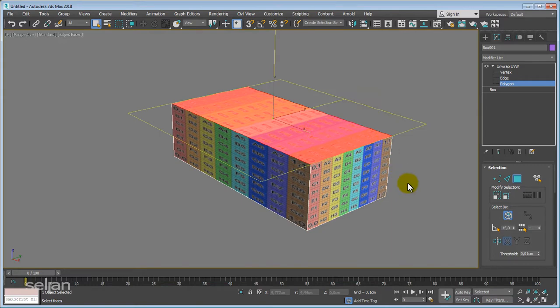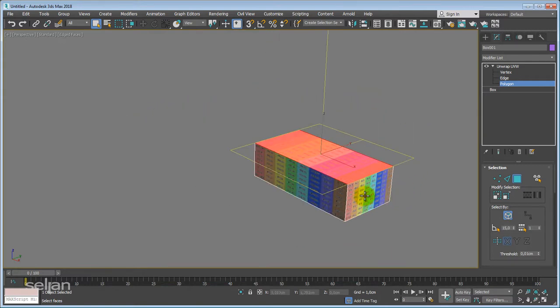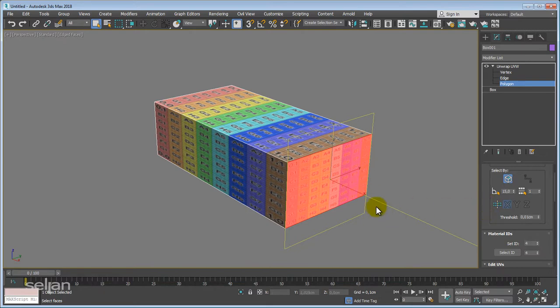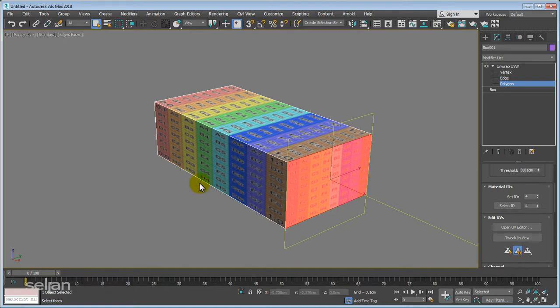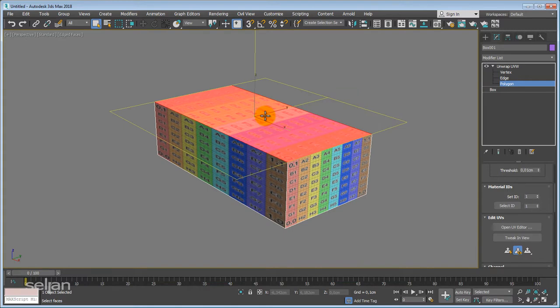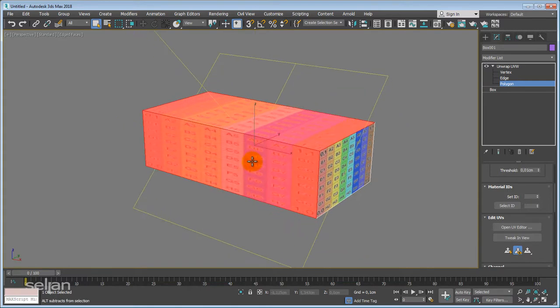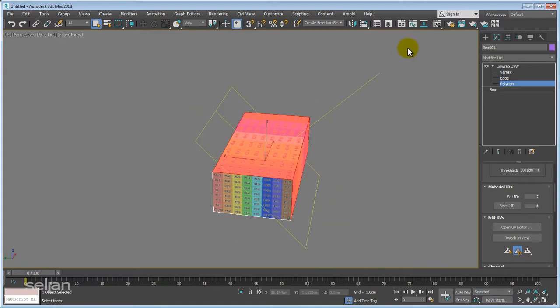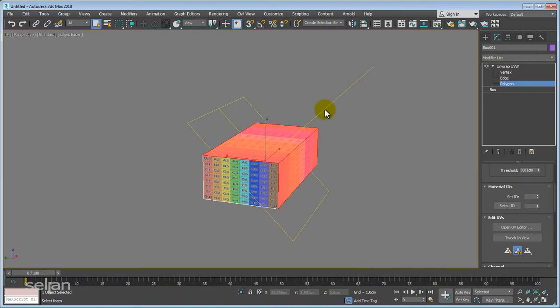and select a face. Now, as you see, whenever you select a face, this quick map gizmo will guess and try to help you with an orientation for a simple projection for that particular face. Now, if you have multiple faces, for example, I'm selecting this one, holding down control, selecting the other one, now we have an average. So the best, easiest texturing projection, if you have a single planar projection face, will be somewhat like this one.